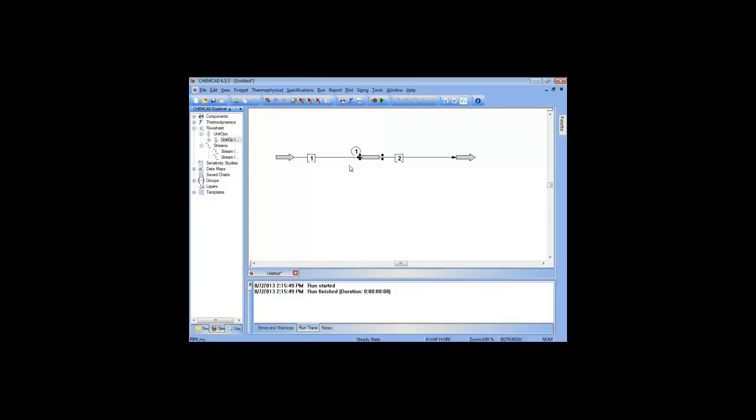If you've got unit operations close enough to each other, you're not necessarily worried about a great pressure drop. It's very minimal. You don't have to add additional unit operations everywhere to account for it all, because it would make the simulation much bigger. But there are times when unit operations are far enough away from each other that you need to take this into account. The pipe would be the exact unit operation that you would use for long runs, big distances, that sort of thing.